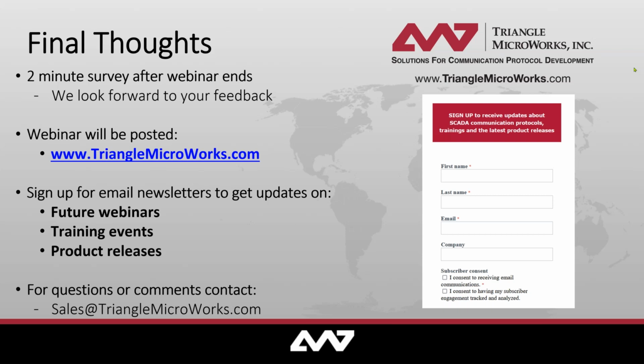Okay. Next question, Christoph, this is for you, specific to 61850. What would happen to a network when there are two IED devices with the same IED name? That would not be a very good idea, because the standard requires that the IED names are unique on the network, because the IED name is part of the address that we use to identify the data. So typically you have naming schemes for how to create these names so that they remain unique.